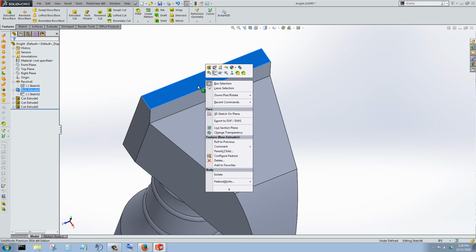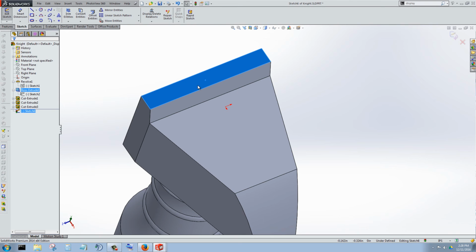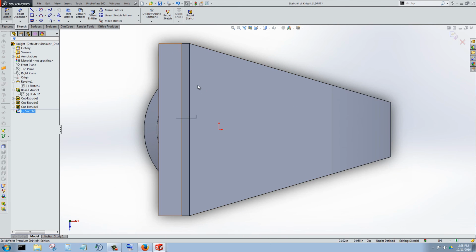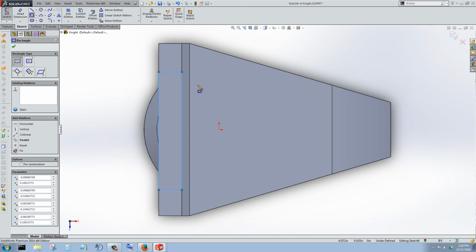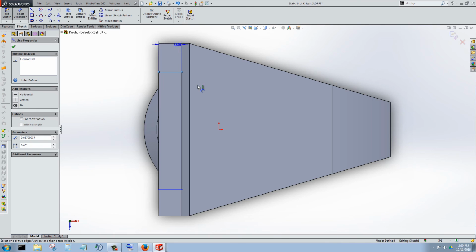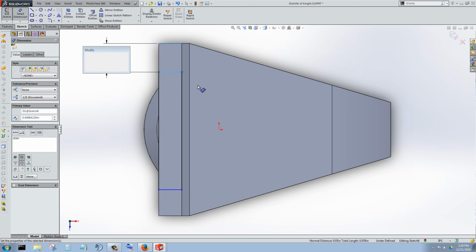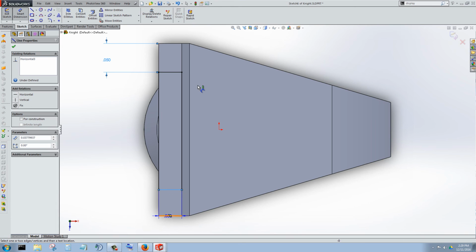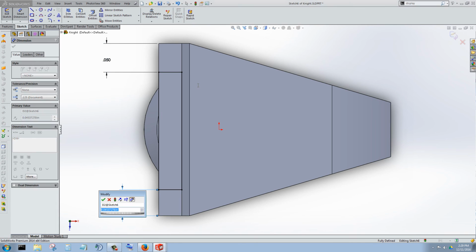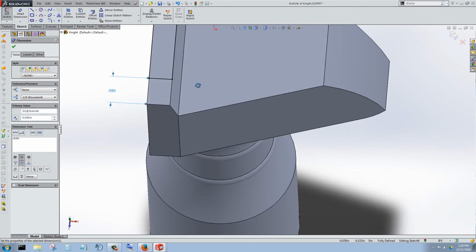Tell you what we will do now is we'll sketch on that plane and go normal to it and cut out the area for its ears. Okay, and let's just see what the distance here is. Let's just make it 50 thou, and we'll make the distance here 50 thou, and that comes at a diagonal.